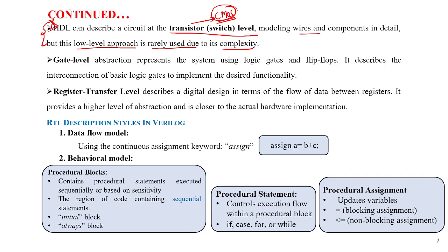If you are designing any SOC, IP or microprocessor, the program becomes very complex, so you can't use switch level modeling. Next is gate level modeling, where you represent your system using logic gates and flip flops. It describes the interconnection between basic logic gates to implement the desired functionality. We'll discuss gate level and switch level modeling in detail.